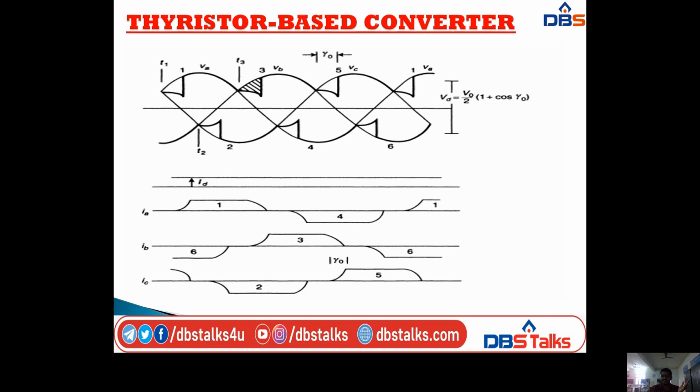In the three-phase full wave diode rectifier operation diagram, on the left side it consists of the three-phase supply, that is three-phase terminals with a neutral connection N. On the right side we have the three-phase diode connection, using six diodes numbered 1, 2, 3, 4, 5, 6, and one inductor or reactor connecting to the DC supply.